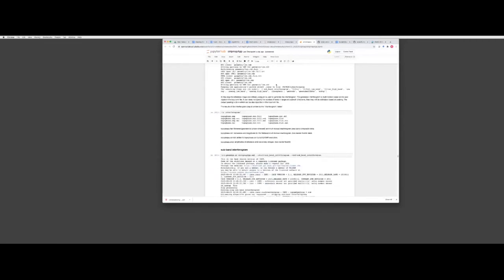All right, so we have two co-registered SLCs. The reference and secondary images are now on the same grid. We just need to cross-multiply them and get an interferogram. So the exciting part is getting close.